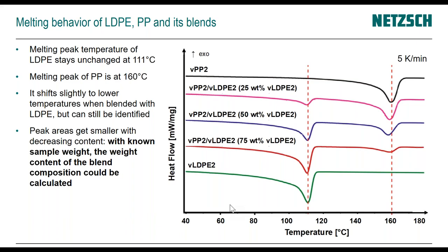Yeah, and the last thing, that's a little bit off topic, is the working principle of the hot stage microscope. You put a small quantity of material between two glass plates, put that in a little heated box in your microscope. Cooling rate is relatively low. Isothermal measurements are ideal. The cooling rate you can achieve is 3 Kelvin per minute, maybe lower, maybe 2 Kelvin per minute.